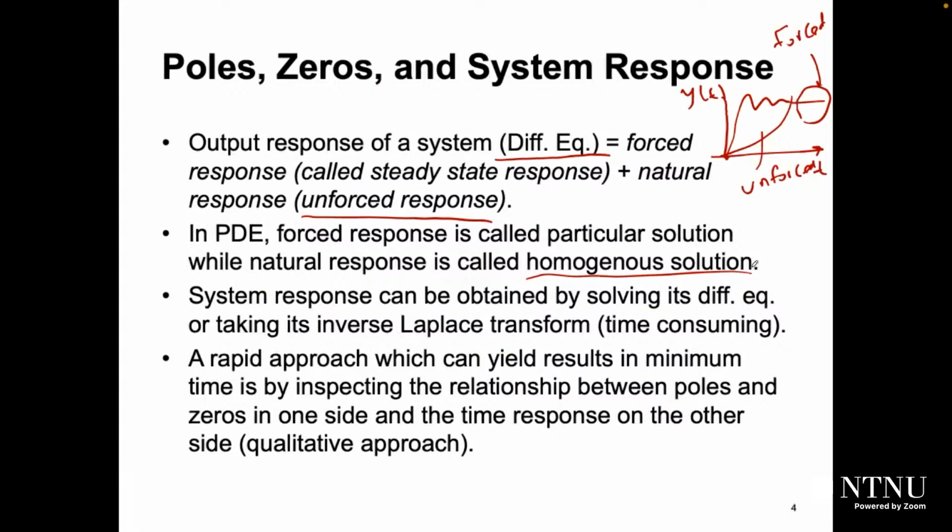So when we have a complex differential equation and we need to solve it, one way, in fact, is to solve it in the frequency domain. So we apply the Laplace transform, we simplify, and we provide the input. The transfer function will be g of s equal y of s divided by r of s. We need to get y of s on one side.